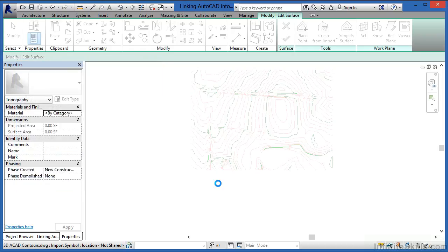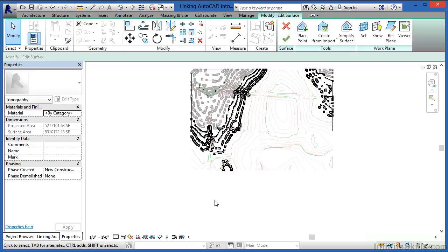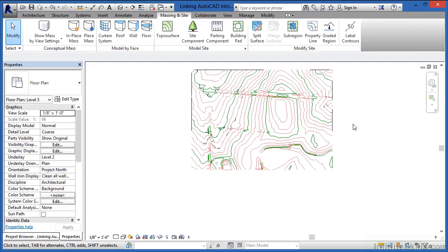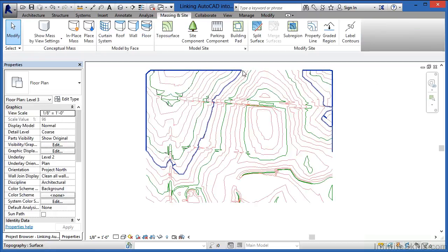because it's currently converting this into a Revit site. Whenever it's finished this process, click on the big green check mark. Now it sort of looks cut off, but the reasoning is that only some of this site is currently going through our current level. If we went to a different level, we'd be able to see different parts of the site instead.